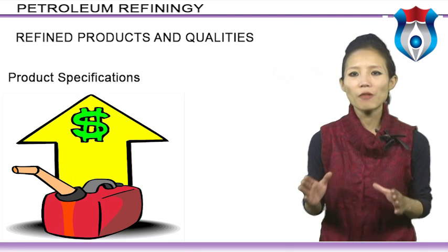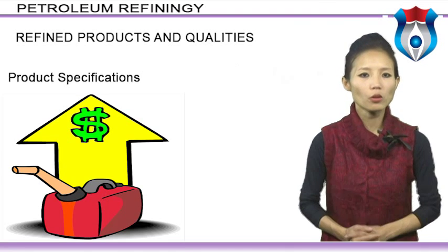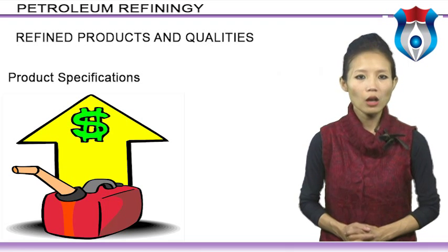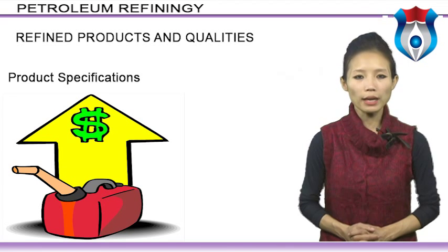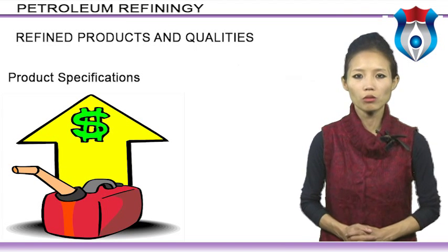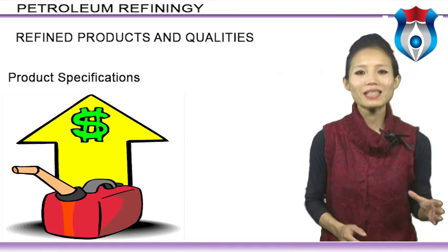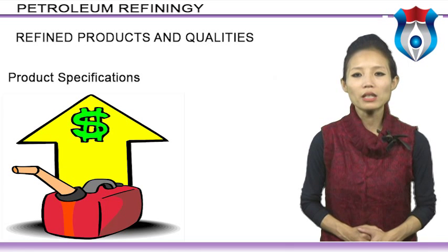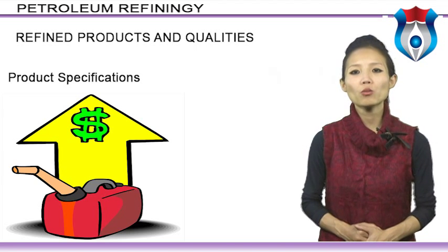Most people are familiar with the gasoline octane number. It is the number that you refer to when selecting the grade of gasoline to use in your car. The number may be 87 or 89. The vehicle manufacturer recommends a certain type of fuel to be used. In most cars, this is 87 octane unleaded gasoline. This octane rating is actually the average of 2 tests that are run on the finished gasoline, the research octane and the motor octane.